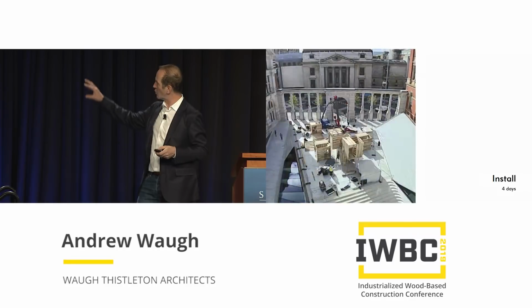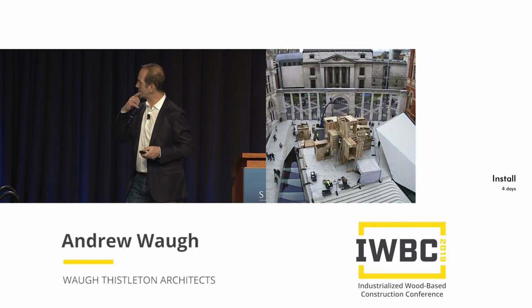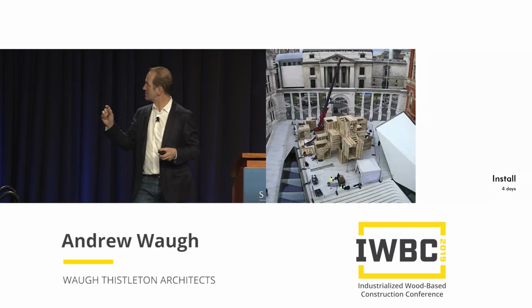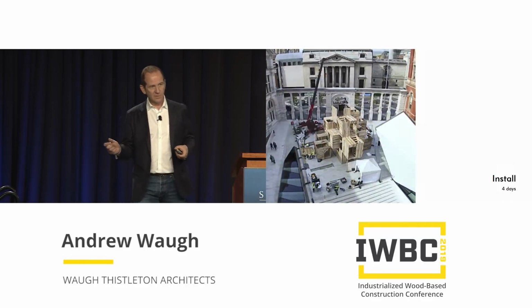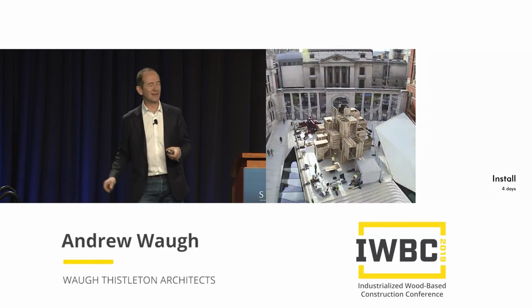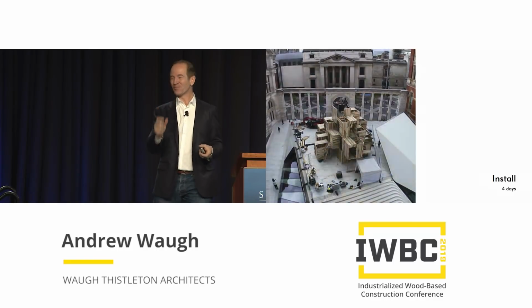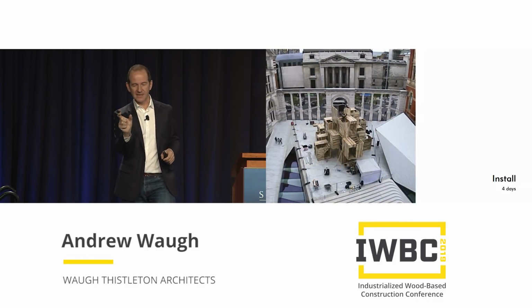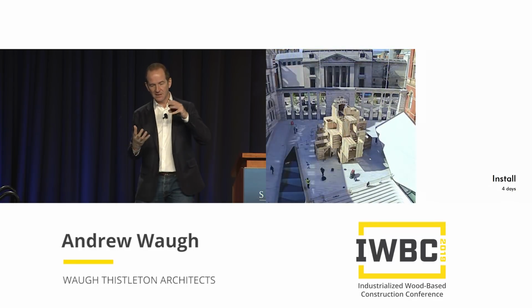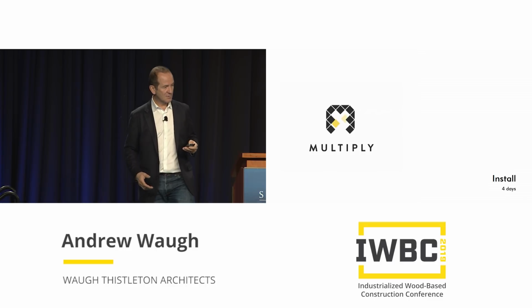So 4 days, brought them in, little spider crane, lifted them up. These boxes are primarily 3-ply. So that's, what is that, 90 mil, 3 times 9, 27 plus 5, 20, about, not much. Less than 3 inches thick. No, sorry, just over 3.5 inches thick, CLT. And each one of the boxes has the loading capacity for 30 people. So incredibly strong